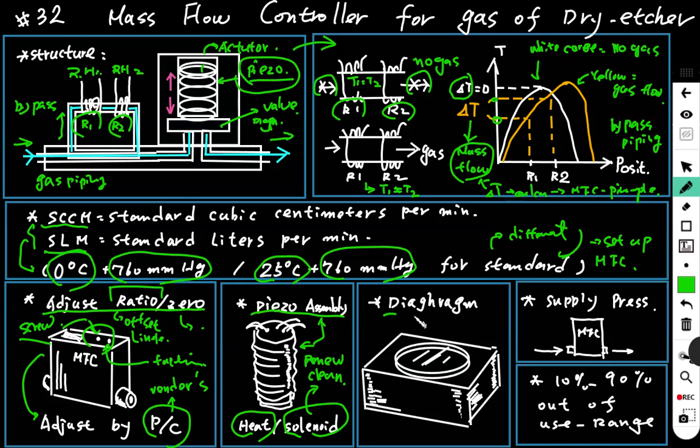Then you can see the diaphragm inside that works as the valve. Maybe it gets dirty, and you can clean it. If the diaphragm valve or its O-ring fails, you just renew it or clean it.